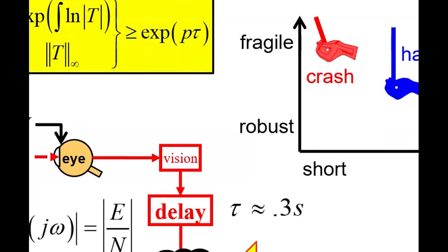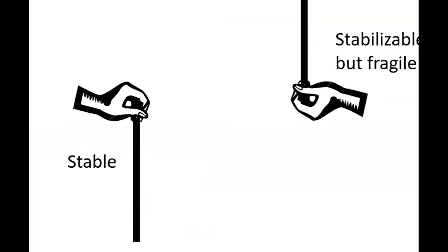Is your T the transfer function of a linear system? Yeah, T is the transfer function. If I have a disturbance in my visual system, a little noise in it or something, it's the noise to this error, and that's what we call T. It's a linear transfer function. So this is the linearized equation. That's a key point here. This generalizes to nonlinear. It's not a big deal, but we don't really need it here. And the tau here is maybe 300 milliseconds because you have the whole visual system, and then you have the actuation.